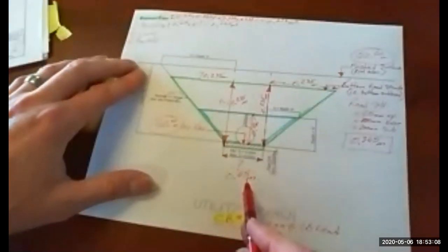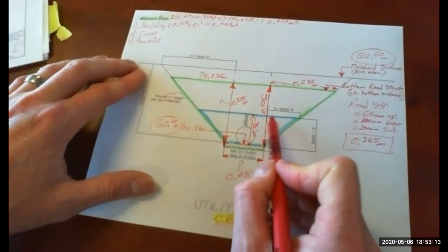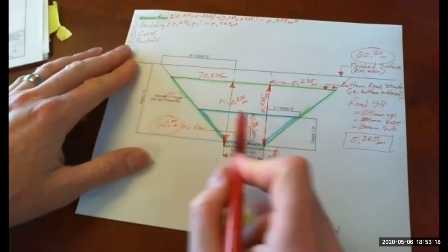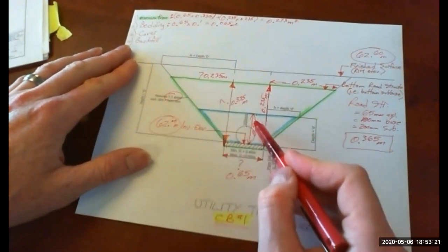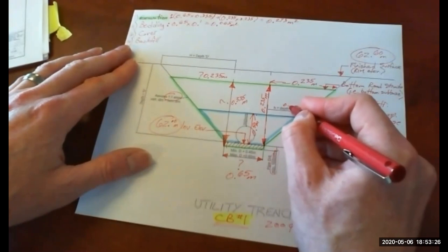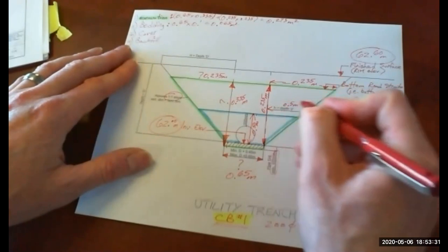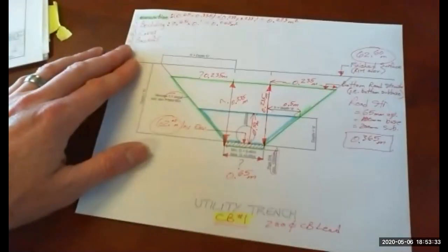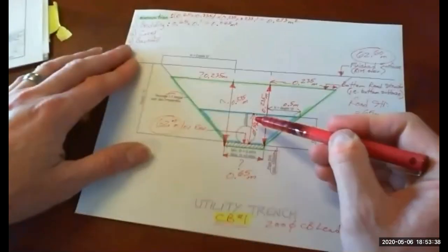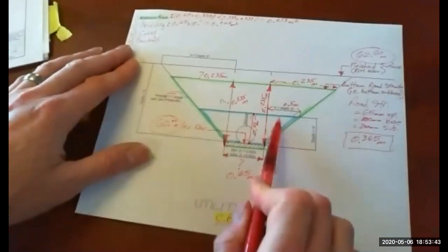And we already have the width. So then what does that make this width here of the triangle? It's the same as that depth, right? Because again, we're 1-to-1 slope. So if we're 0.5 meters deep, this triangle here is 0.5 meters wide also, from there to there. Okay, so area of the blue then is 0.5 depth times 0.65, and then we would add the triangles.